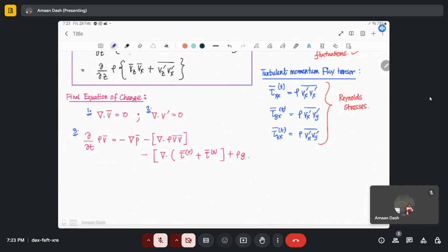That is these Reynolds stresses that we have above that are related to the velocity, but you can see these Reynolds stresses are not related to velocity gradients directly, but rather they are complicated functions of position and turbulence intensity. Therefore, we cannot solve these expressions directly.